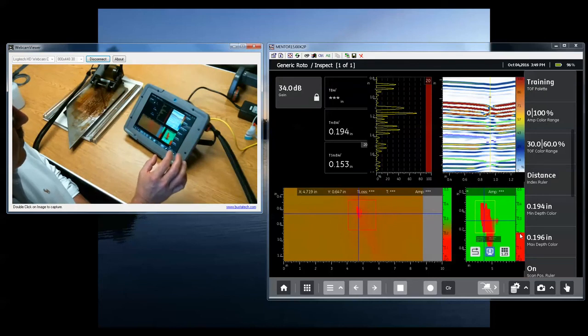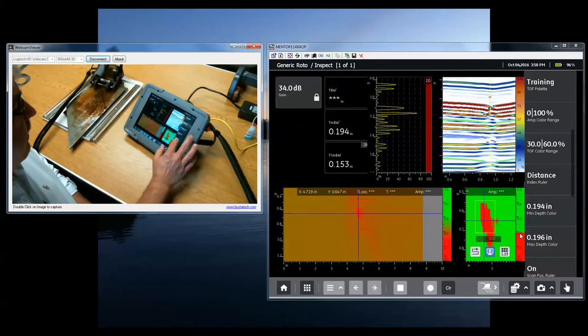When you build your app in Create, think about whether you would rather work in percentages or absolute numbers. For most applications, you're going to want to work in absolute numbers. So I would either hide this control or lock it, take it away. If you would rather work in percentages, leave that control and hide the min and max depth controls. I would choose one method or the other. For most thickness type applications, I would leave the min depth color and max depth color.